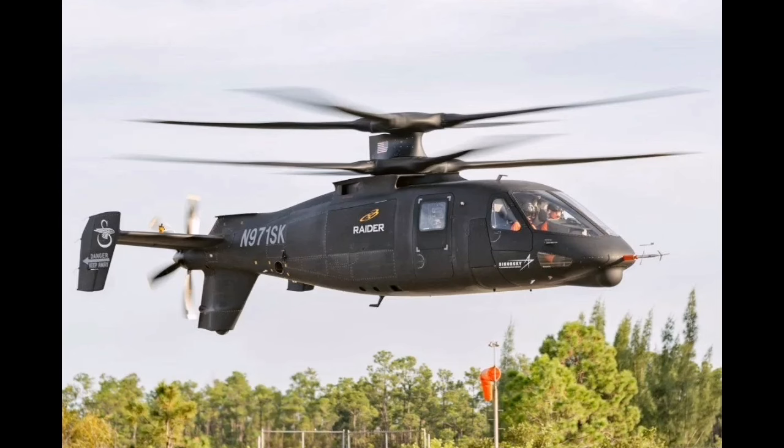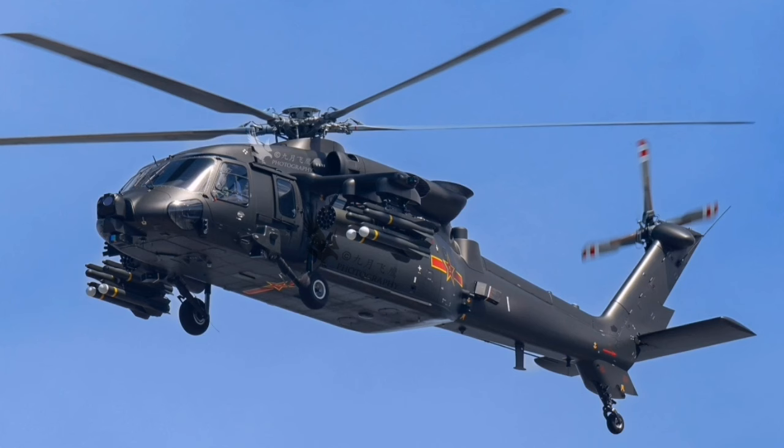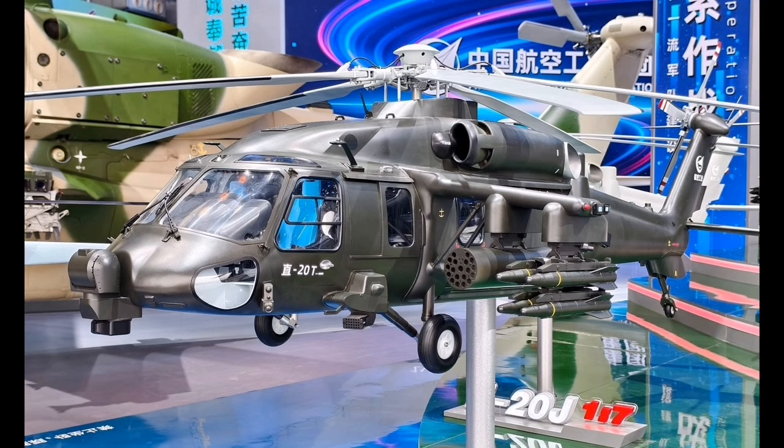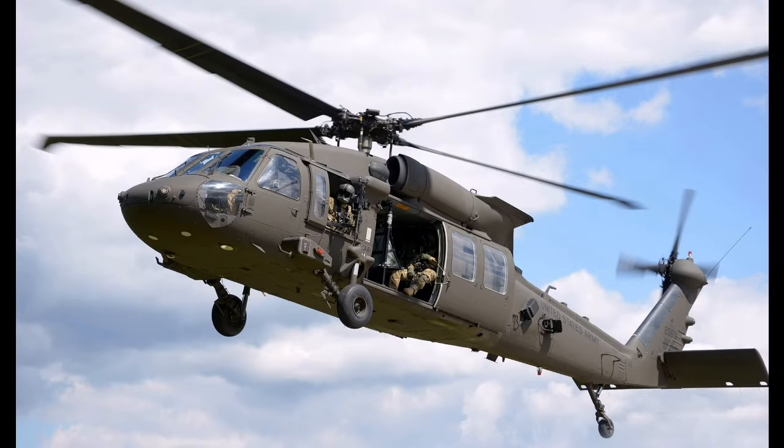The 5-blade main rotor system is a critical design feature, providing significant advantages in terms of lift efficiency, disc loading, and acoustic signature reduction compared to older 4-blade systems. The additional blade allows for a slower rotational speed for the same lift, which reduces vibration and noise, factors that are crucial for both crew fatigue and tactical surprise during low-altitude ingress.